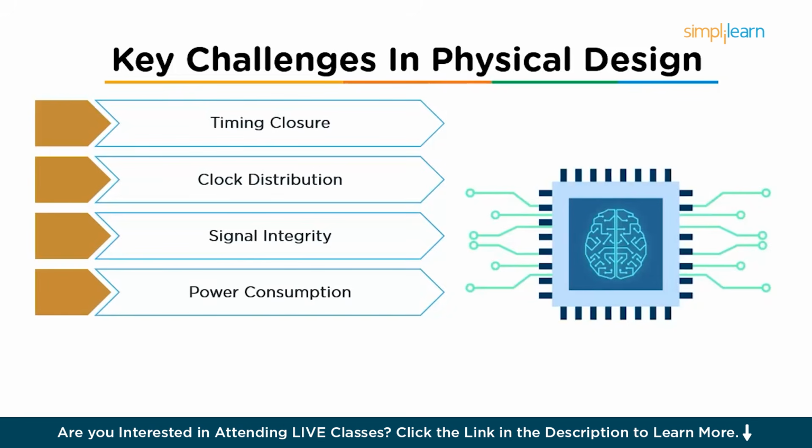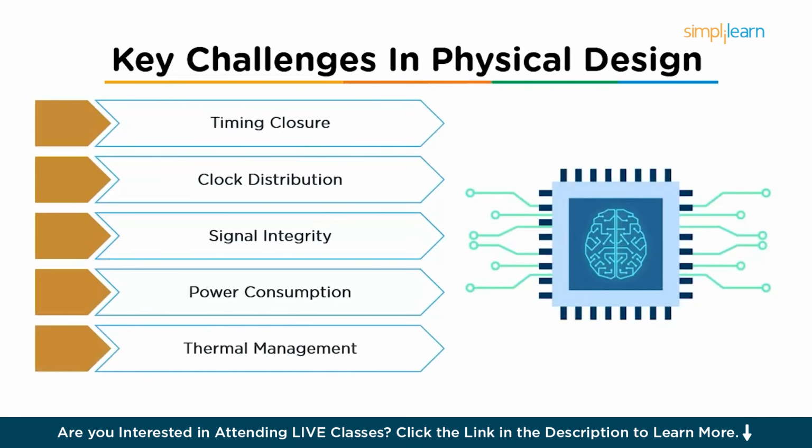Then comes power consumption. Power efficiency is crucial, especially in battery-powered or heat-sensitive devices. Dynamic power and static power must be minimized through smart cell placement, use of low power libraries, power gating, multi-voltage domains, and clock gating strategies during the design.